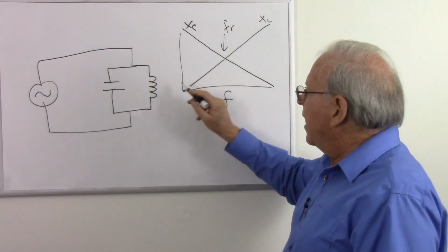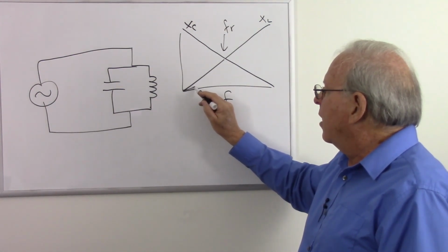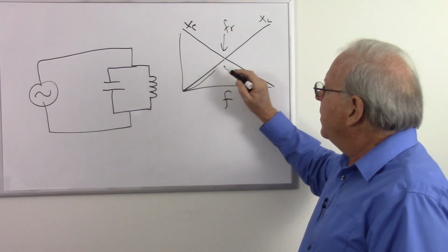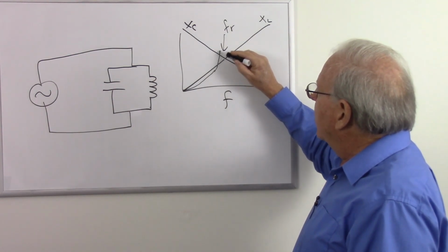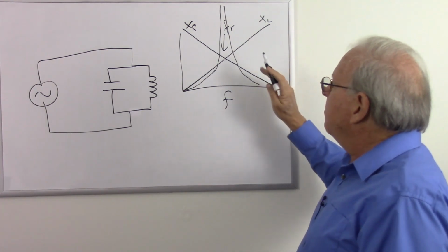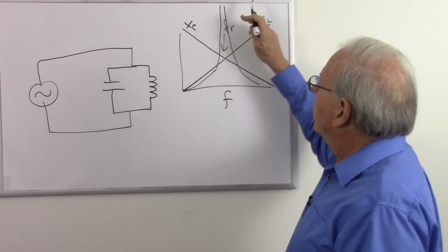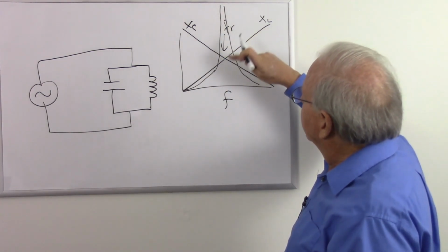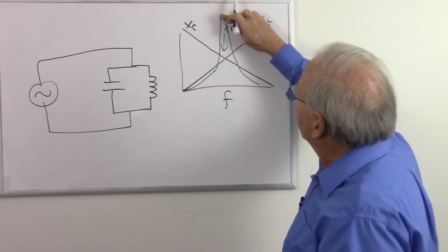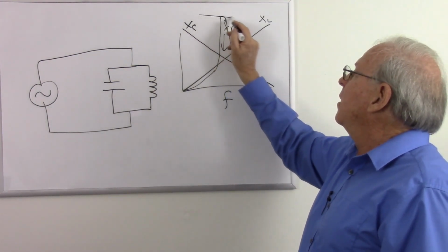The way this is going to react to our voltages is, at low frequencies, we're going to get a low voltage across it that's going to climb and climb and climb. At the resonant frequency, that's going to want to go to infinity and then come back down as the frequency goes up. But in reality, there's going to be resistance in the circuit, and any resistance is going to bring down the impedance, and so that's going to lower that down. The maximum impedance will be the resistance.